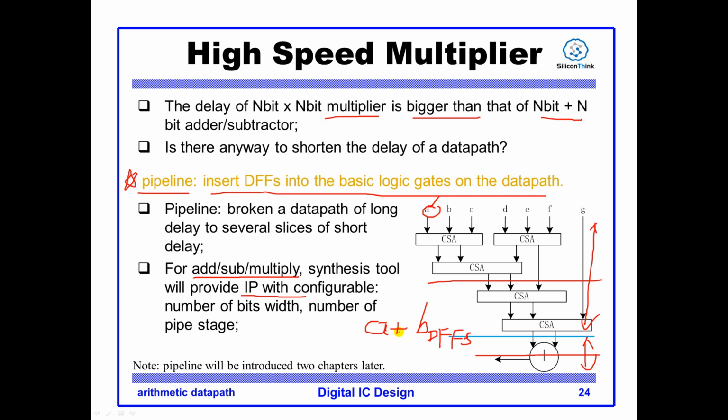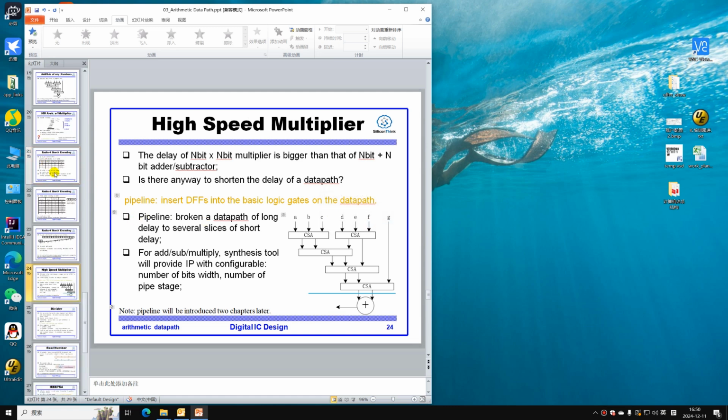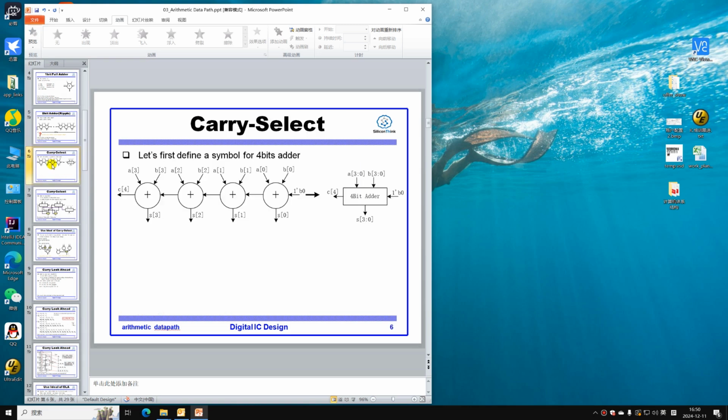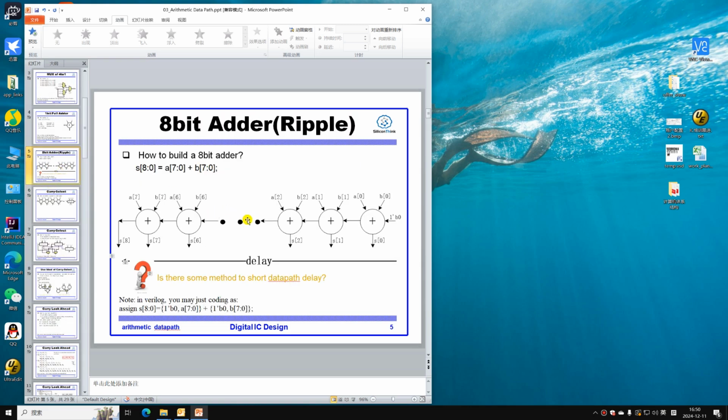Is an AND something that can be divided or can't be divided? In a C program, you will think the AND is an atom which can't be divided, but in a digital circuit you can divide it. Yes, in a digital circuit, you can divide the AND. The AND is made of gates, so you can add a pipe stage at this point.